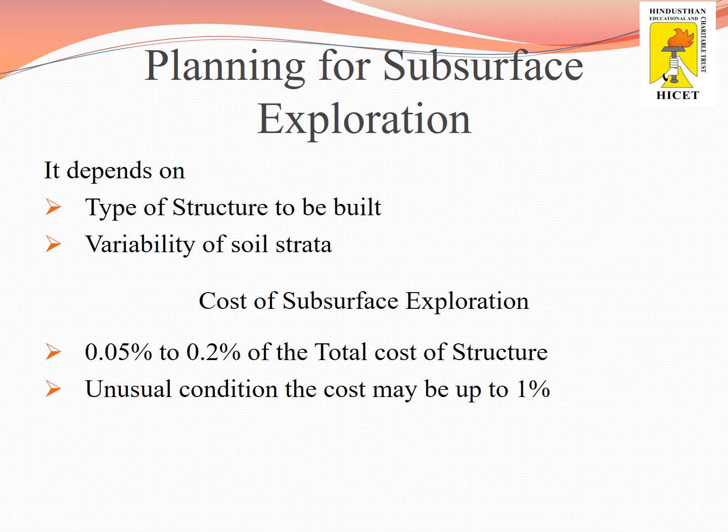At the same time, if we are going to conduct a subsurface exploration for a multi-story building, it is a must, because multi-story buildings impose very high load on the ground up to a greater depth. Another aspect to be considered in the planning of subsurface exploration is that as the variability of soil strata increases, the investigation process should be increased.